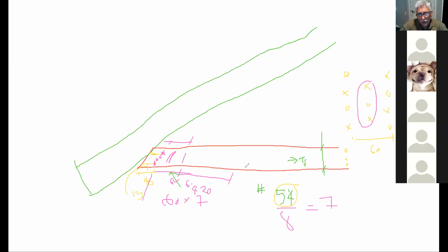And then I'm going to keep an edge distance here of 40, and then distance to my gusset plate. You follow? So now I would take the furthest distance here at 40, and then I would simply go straight up like this, and then this ends up being my gusset plate. Go like this and go straight down here. And I wouldn't worry about here, because if I made the allowance here, the same allowance would be up there. So that ends up being the size of my gusset plate right there.